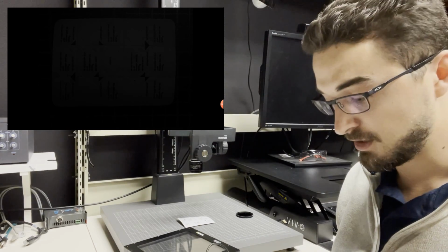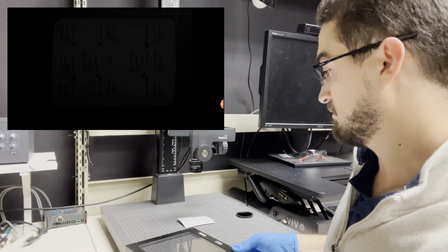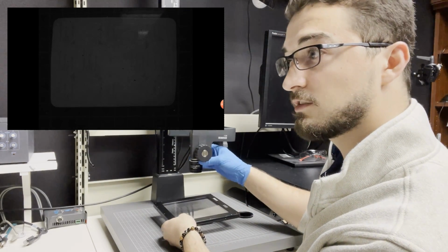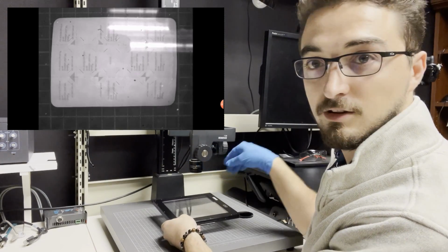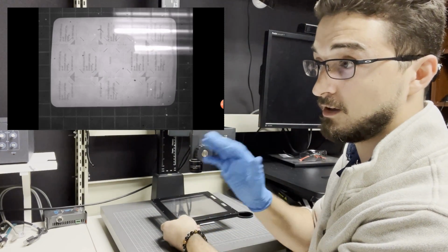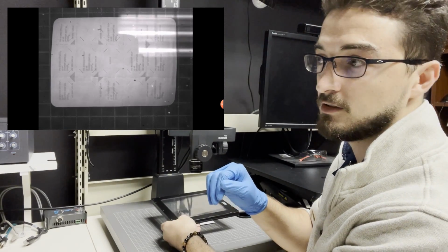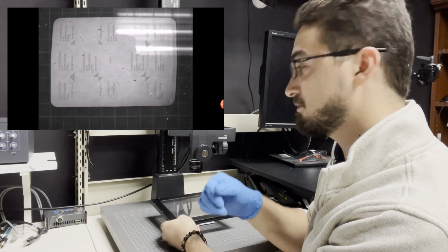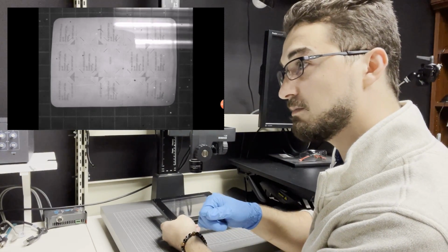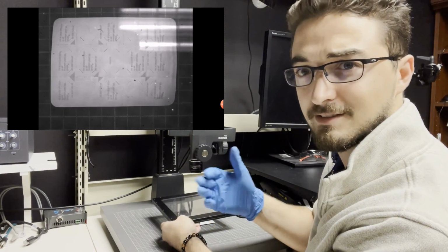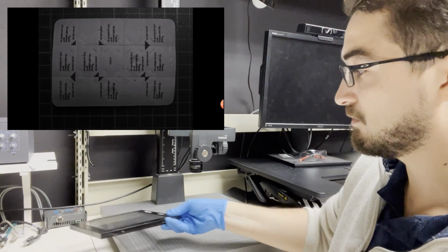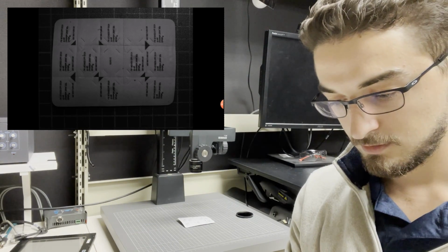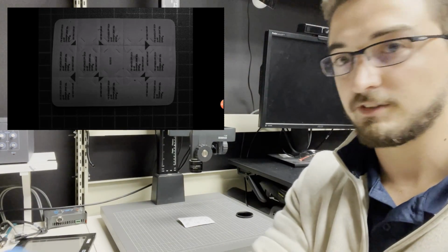So we're going to use the IR dome light, the flat dome light that we have. It is 850 nanometers. So we're going to put that over. The reason why I wanted to show this one is because at the wavelength 850 nanometers, there is still texture. So we would need to go higher. And I would mess with this a little bit more, but the defect still cannot really be seen from this. So we're going to move on to the backlight again, of the 950 nanometers.